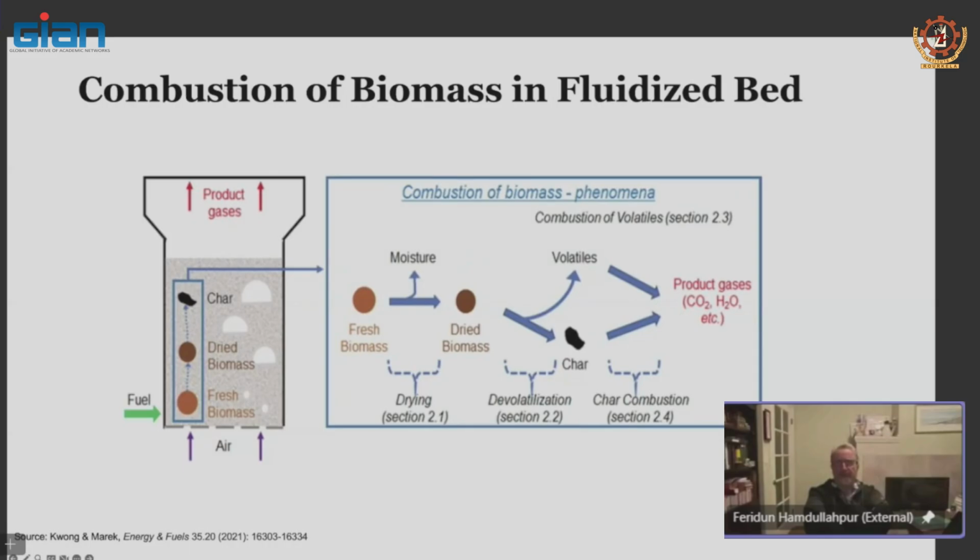It's a byproduct, it's a biomass, or simply waste from a number of municipalities, including if you have a sewage treatment plant, the sewage, the sludge. They are all biomasses, and they come in with high moisture ratios. So every biomass combustor will have to have a drying, either within the bed or adjacent to the bed, a dryer before it comes in there. So you have fresh biomass, it enters, you have to dry to a level, remove the moisture, for which you're going to spend energy.